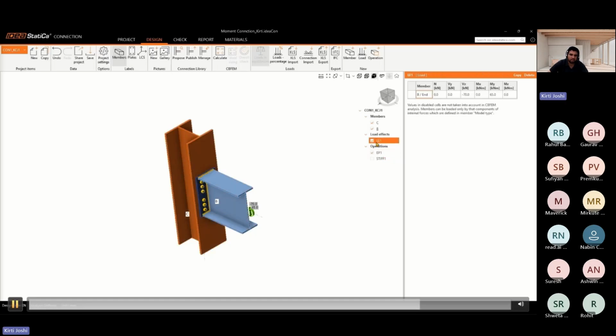So you can set out the buckling length, and in the load case, you can define your load. The next is, once you provide the stiffness length and select the analyzed member, then you can input your moment value. Right now, by default, there is the shear force and the moment. So I'm just creating two different load cases, copying the load case, and in that case, I'm just assuming the moment only. So there are two cases that I will run for this.